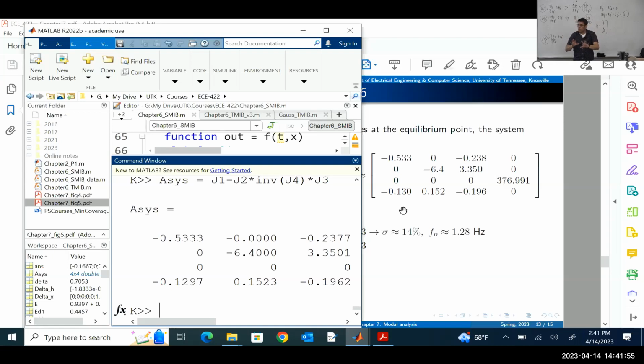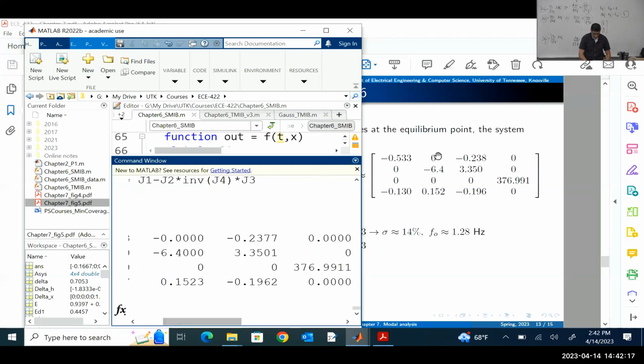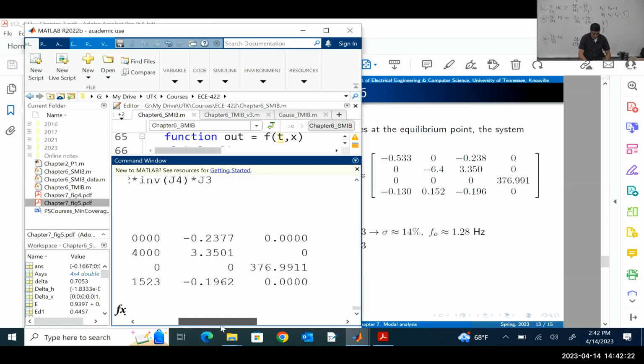By doing the partition, we separate what are algebraic equations from differential equation and algebraic variables from state variables. You partition the system, and then you apply the Kron reduction to obtain the system matrix. Okay, as you can see, we get the same result. Let me move this here. This second column is about the same. This one, yeah. It's just rounding numbers, right? So if we round this to 3 decimals, we should get the same result.